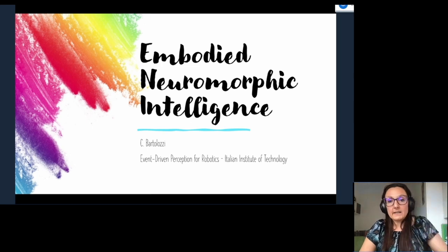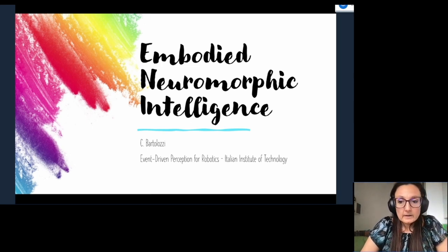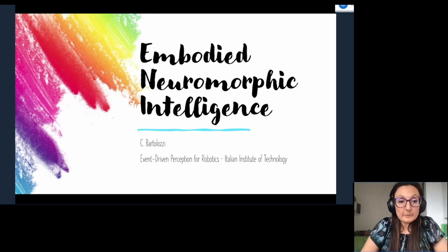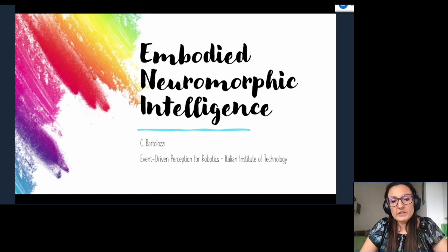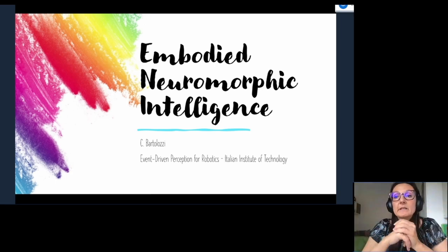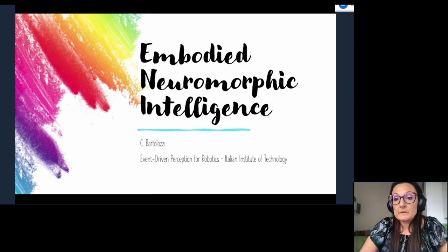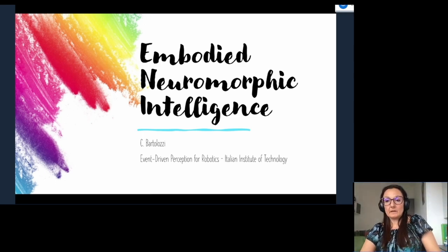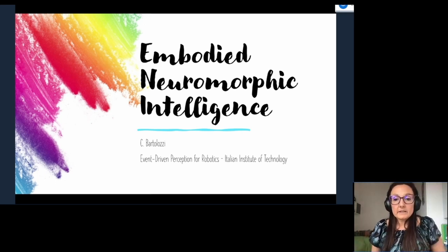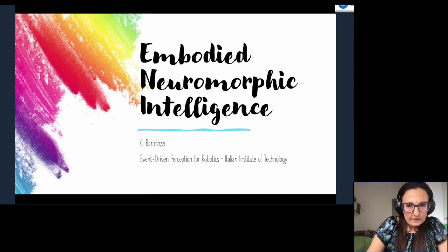And then you can also run it on more complex stimuli. And you can also, for example, add depth information. In the original frame-based implementation, they use the color image and the depth image from a RealSense sensor. We could use events from stereo event cameras, from the left and the right camera. We could use a disparity map implementation from the events, and basically give priority to stimuli that are close by.